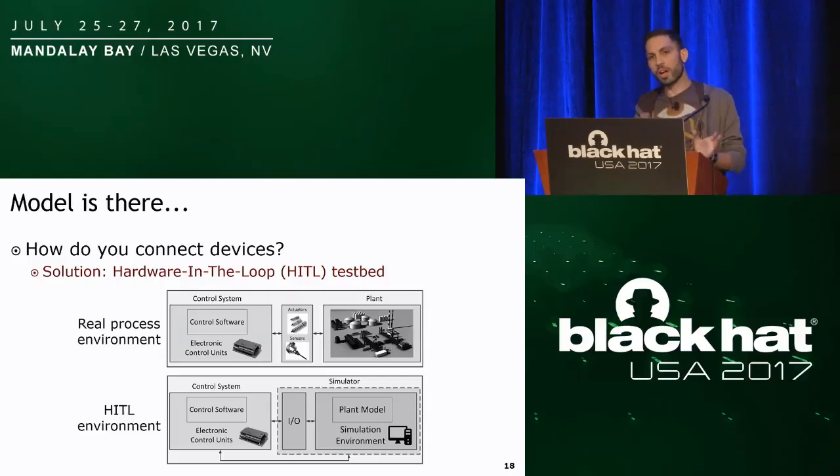So one or more hardware devices, a PLC, a relay, or in general an electronic control unit, are connected to the host computer that runs the simulation model. This allows us to have a flexible, reconfigurable, and modular environment to emulate different conditions, examine several scenarios, and test actual real-world interfaces without the hazards of a production environment.